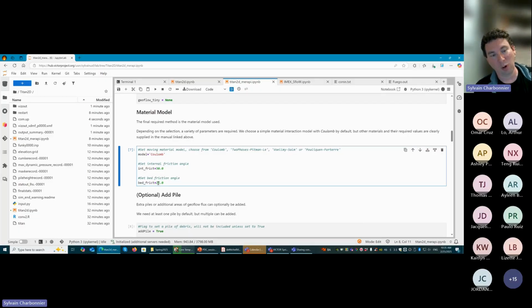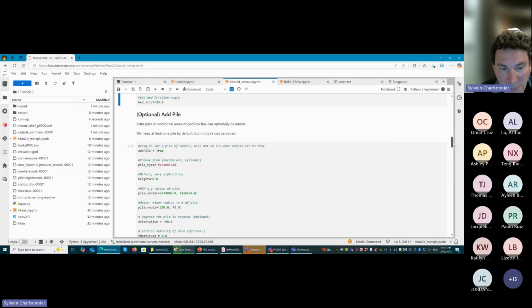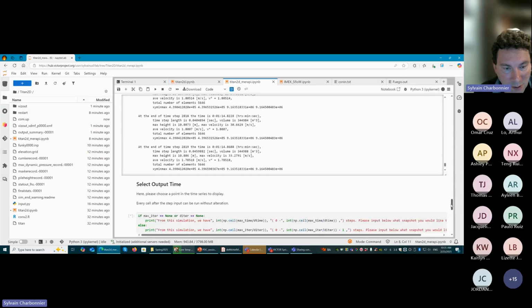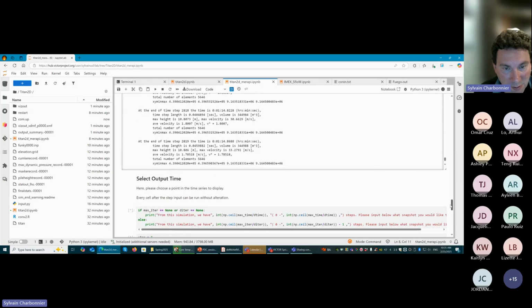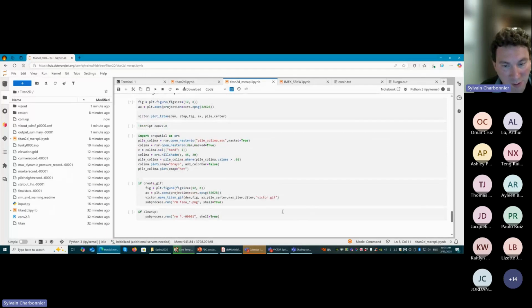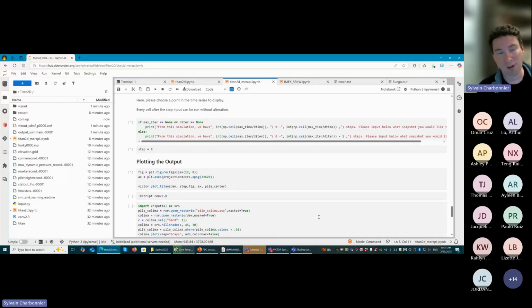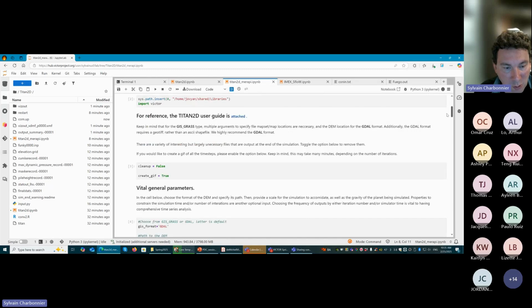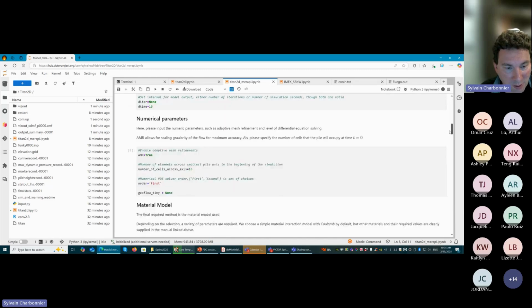So you put a lower value and compare the map that you get, especially the one with the R script, the footprint of the flow inundation. You're going to see that when you lower that basal friction value, you're going to get a flow that is much more mobile, that's going to be able to overcome some obstacles in the topography, like some ridges and valley banks, and it's going to go much further down the slope of the volcano.